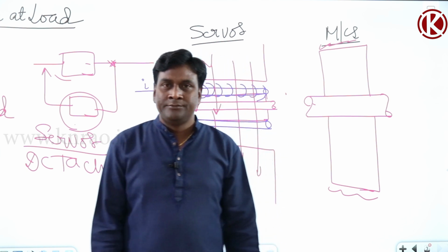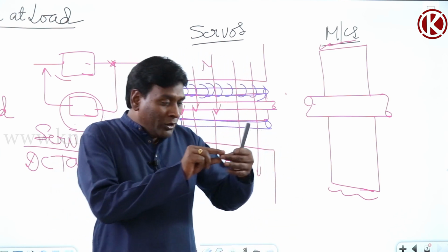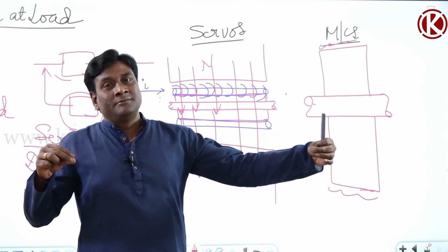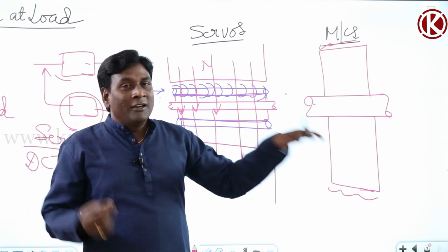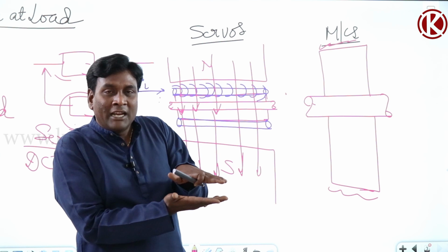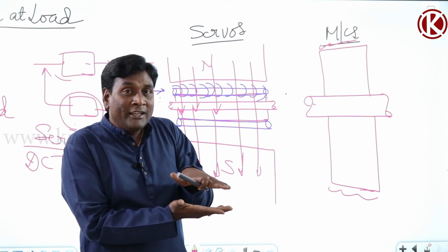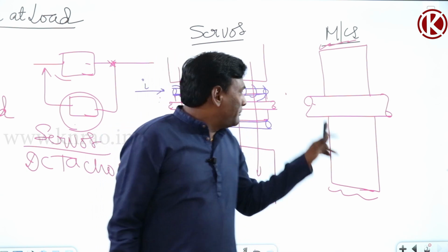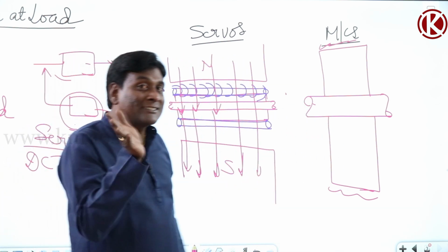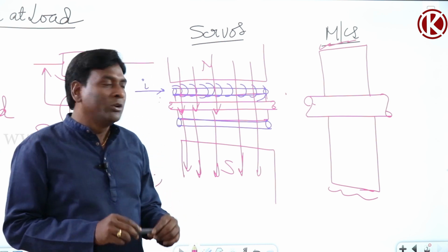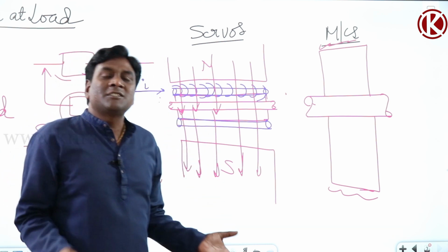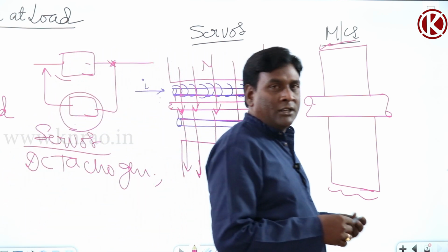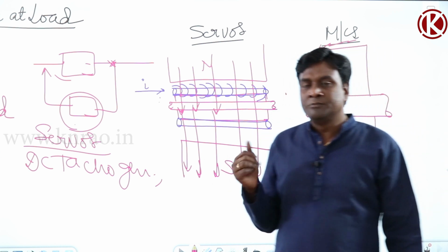But in the servo, length of the shaft is increased and diameter of the rotor is reduced, in order to reduce time constant. Increasing length of the shaft will not increase price of the servo, because mechanical stress will not be there on the shaft. Normally, people will ask these two interview questions.